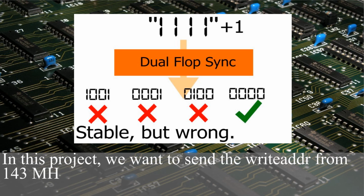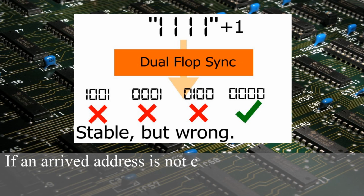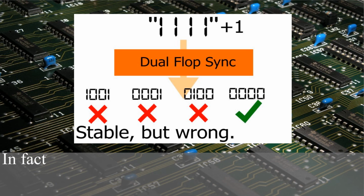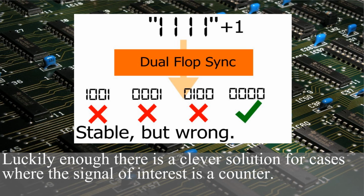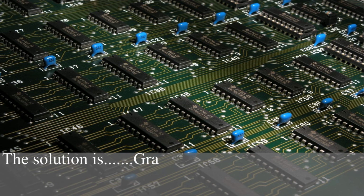In this project, we want to send the write address from the 143 MHz domain to the 49.5 MHz domain to detect the empty condition. If an arrived address is not correct, the empty condition will not be detected. In fact, the addresses are nothing more than a simple counter, which increases only by 1 at a time. Luckily enough, there is a clever solution for cases where the signal of interest is a counter. The solution is gray code.